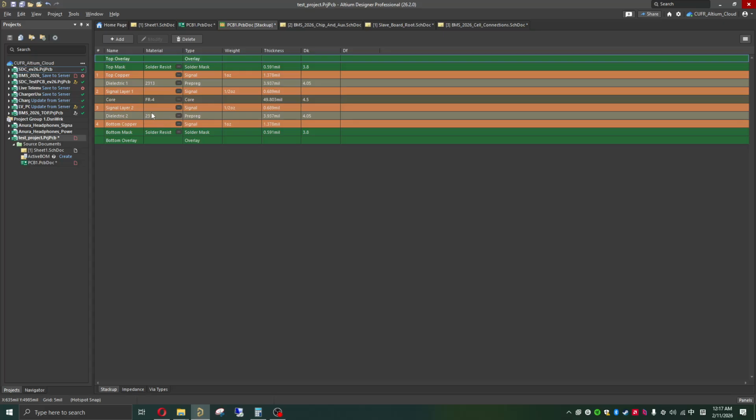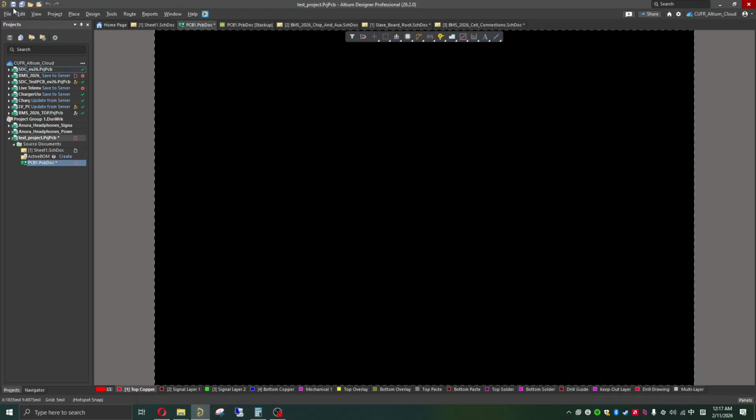For the dielectrics, it's going to give the proper values and stuff. And this is important if you have a workflow with an electromagnetic simulation software, but we're not doing that one today, but it's good to have this configured. So we have our document, and now we have our StackUp configured.